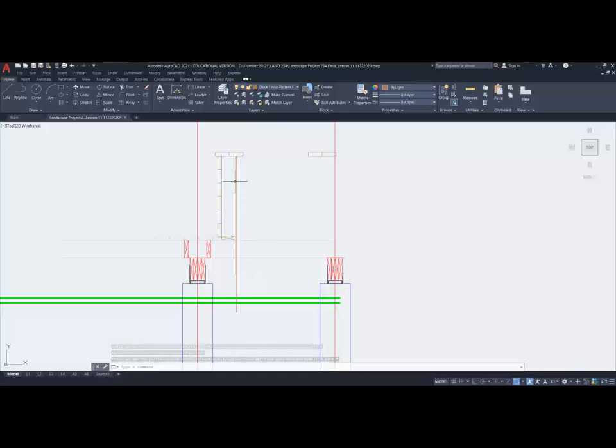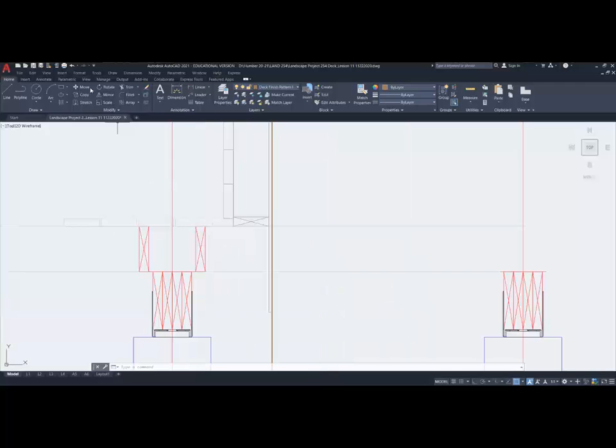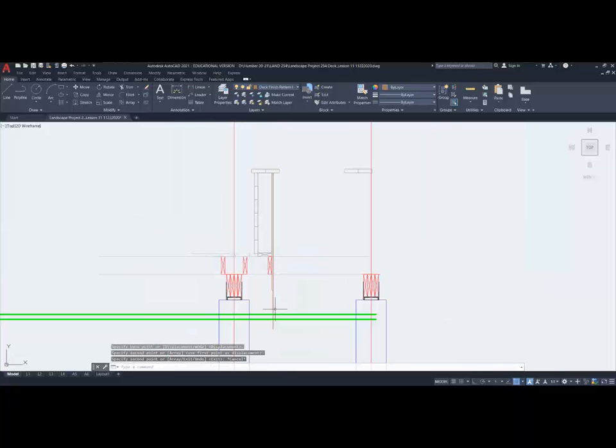So what have I actually done here? Well, I'm creating an inside wall where the soil can then be built up to that location. What I do need is some backing or some framing support. So now I can use this information that I just left, for argument's sake, there. And it's basically providing the support on the plywood itself. And then we have this rubber membrane that's coming in through here. This is the detail I'm going to be drawing to make my planter.